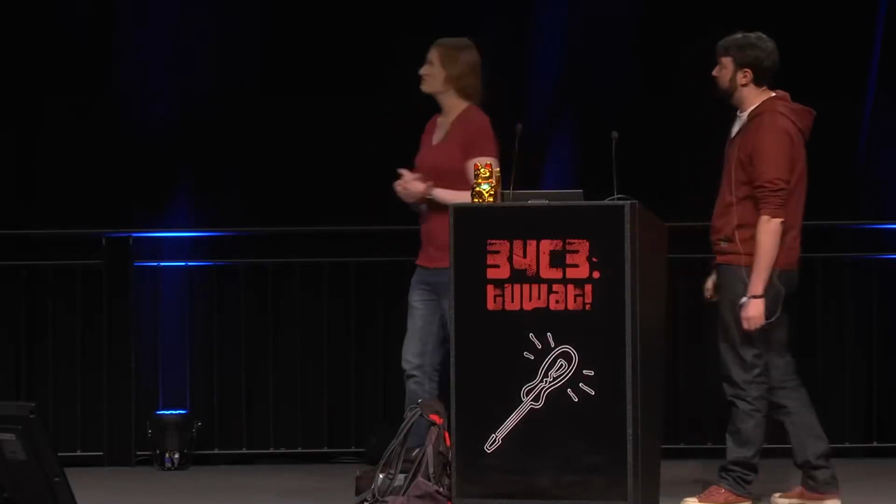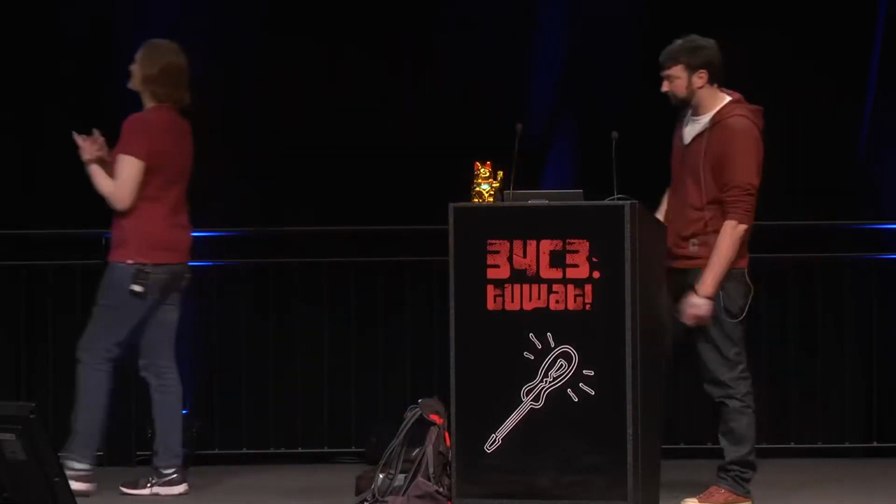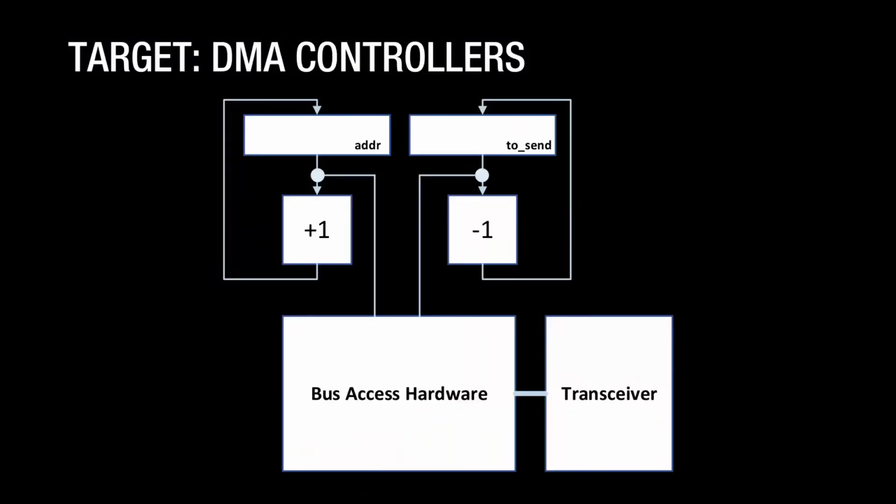Right, and so this may seem pretty synthetic. That may seem like the kind of code that you'd hopefully not see in a lot of programs, depending on the use case and the constraints. But this is exactly the way in hardware a DMA controller works, right? It is constantly subtracting from its length register by 1 or more. It is constantly incrementing the address that it is reading from, the address that it's sending down the bus in order to gather data. So even if that software example looked a bit synthetic, it is absolutely applicable to embedded hardware. Yeah, and there's absolutely no error checking, because you've got a DMA controller on a microcontroller.